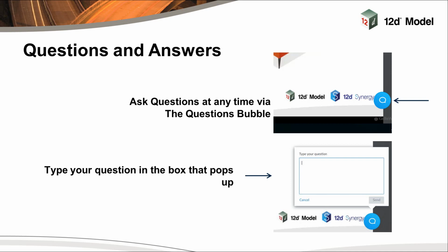So I know a lot of our users who are adopting this, they like having the plan in the left-hand side of the sheet, and they can have a 3D PDF frame on the other half of the sheet. So it produces almost like a dynamic orbiting around 3D result of what's shown in the plan view. And you can have frames over the top of each other. The order in the list is the order that they're plotted, so you can control that very easily within the interface. So if you wanted a blow-up subframe on top of the rest of the data, I didn't go through it in too much detail, but there's an option to white out a frame, so it would basically obscure any of the data underneath that frame.